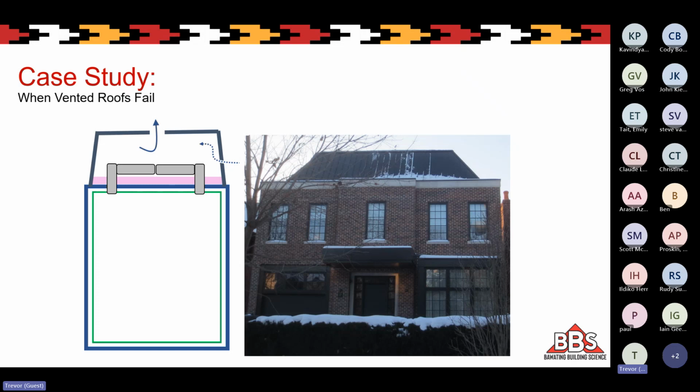So what is supposed to happen in this attic is that air is supposed to come through these really small vents, and I'll show you a photo of them, that are lower down on the steep part of the roof and exit through these larger flat vents on the top. If it worked properly and we didn't have too much air leakage, this could work.